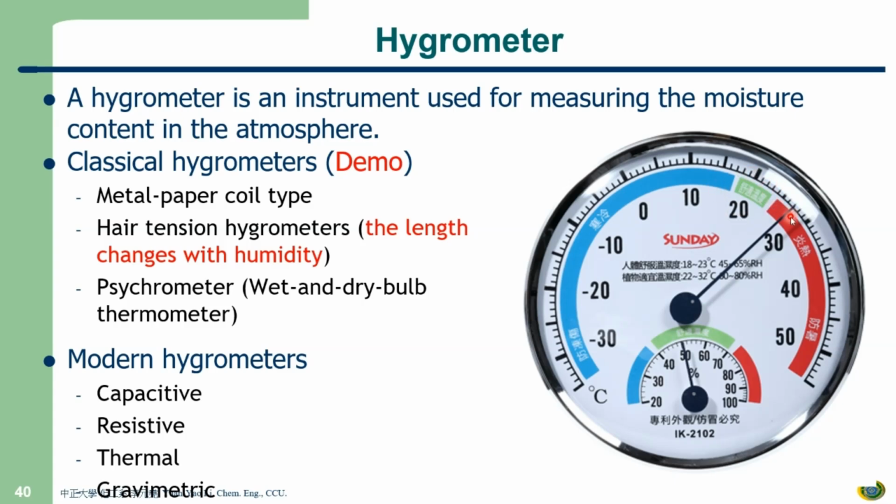If you go up to 30, it's too hot. If you go down to 15, it's too cold. The hygrometer is this one. A relative humidity between 40 and 70 is comfortable, but more than 70 is too wet, and less than 40 is too dry. You don't feel well after 70 or before 40.